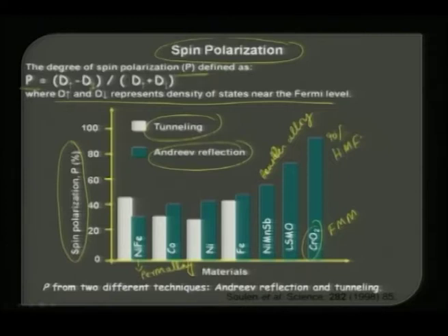So, these are good candidates for electrodes in tunneling magnetoresistance devices. One of the important criteria is that one of the spins should be a majority spin, and if it is 100% spin polarized, then tunneling magnetoresistance can be more pronounced for such applications.